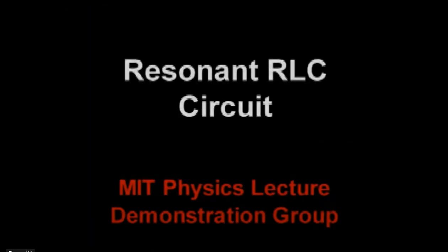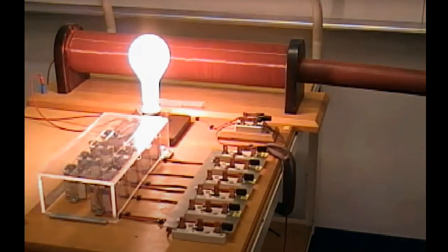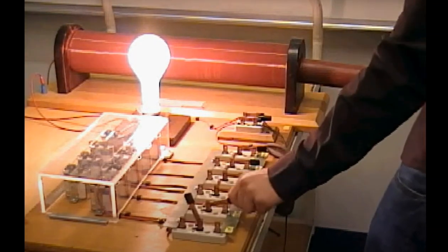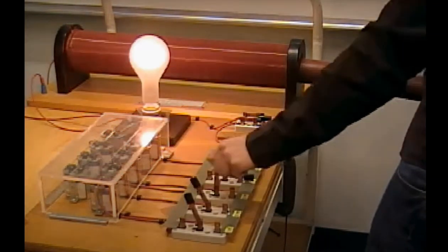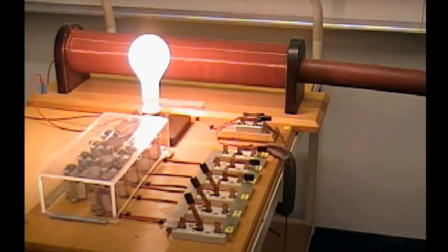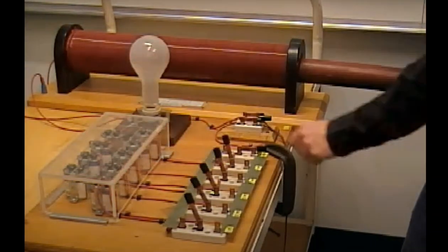Notice he always stops when the light bulb gets brightest, because if it's brightest, then we've achieved resonance. But if he changes C or L, that changes the resonance frequency and he has to change the other to get back to the brightest light bulb.